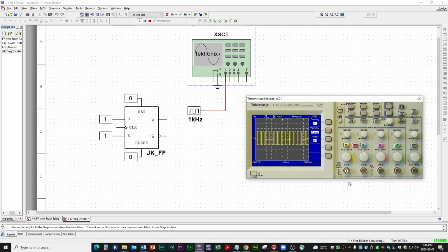Basically, it's the way it's coupled into the input. DC coupling shows us the true signal. Sometimes the whole signal is 100 volts DC, and then there is maybe a 5 volts ripple. In order to see that 5 volts ripple, you want to isolate it from the DC component so you can actually see the shape of the ripple. But in this case, it's 5 volts, from 0 to 5, 0 to 1 logic condition. We want to have this thing DC coupled.